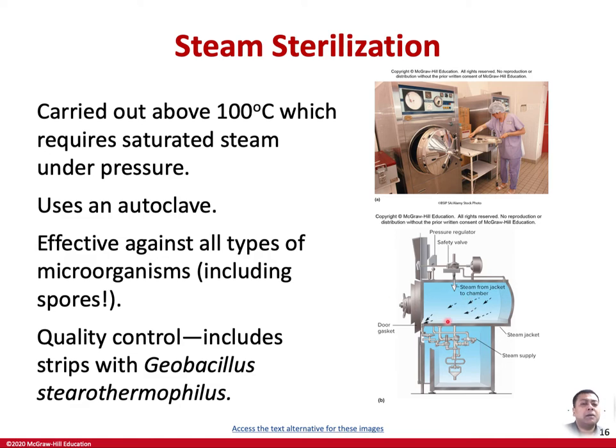If you have material which is completely dry, doesn't have any liquid, you can do a process which we usually call gravity type autoclaving, where the material is completely dry. It is steam sterilization, but the process is a little bit different. Initially the air is sucked out by vacuuming, and then the saturated steam fills up the chamber. Whereas there is another process by which we sterilize liquids. In that process you cannot apply the vacuum initially because the liquid will boil over. So essentially the air is removed by purging steam, and the valve is open until all the air is out and the chamber is saturated with steam.